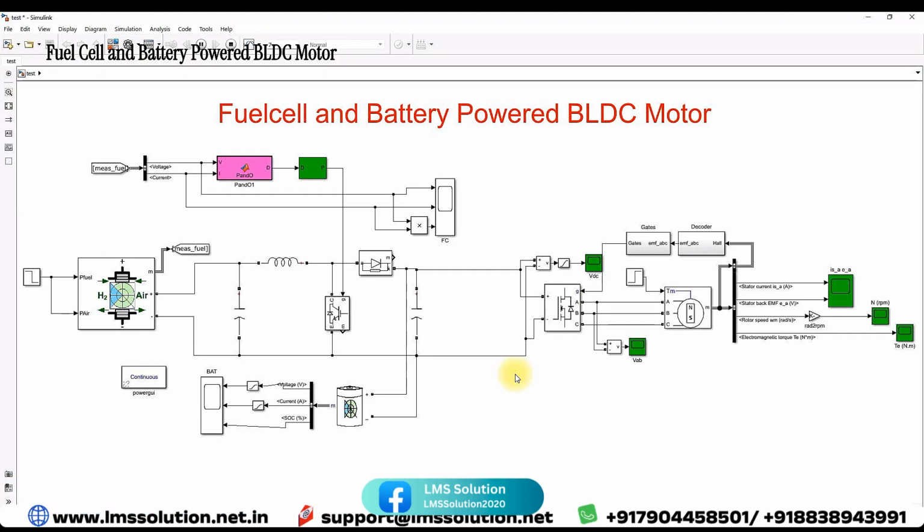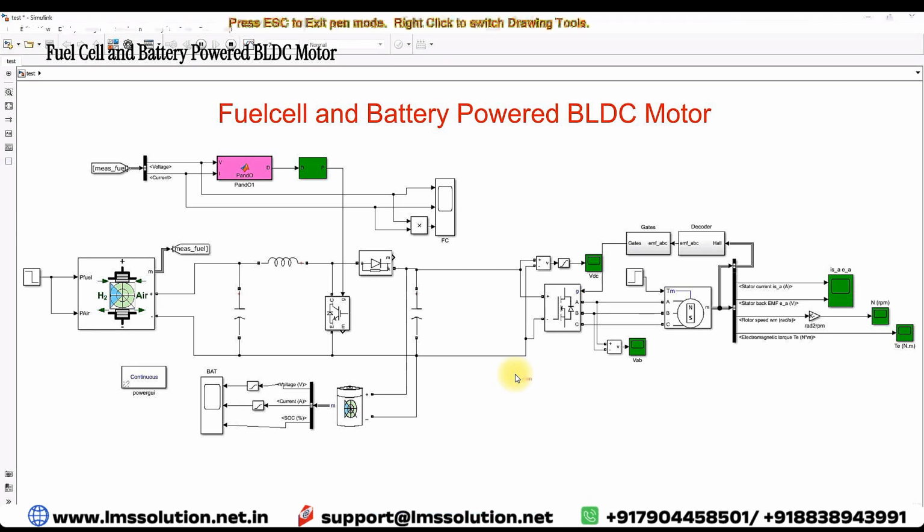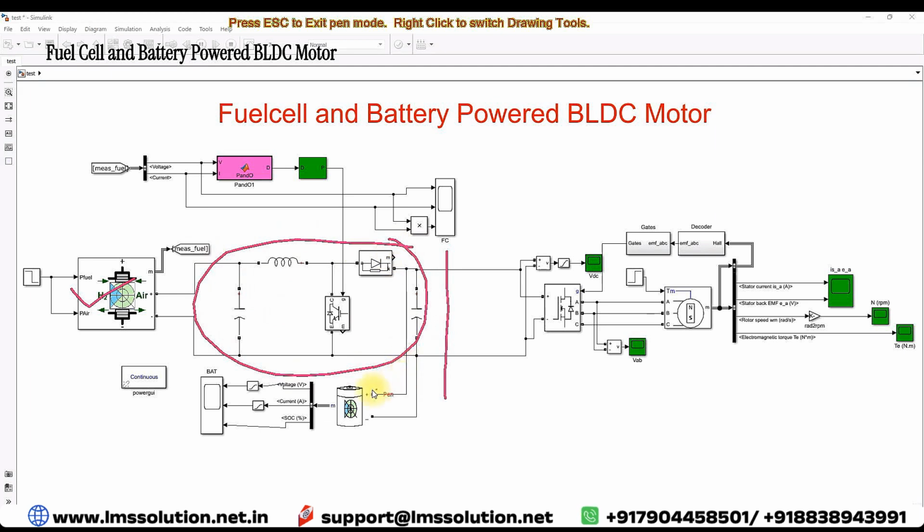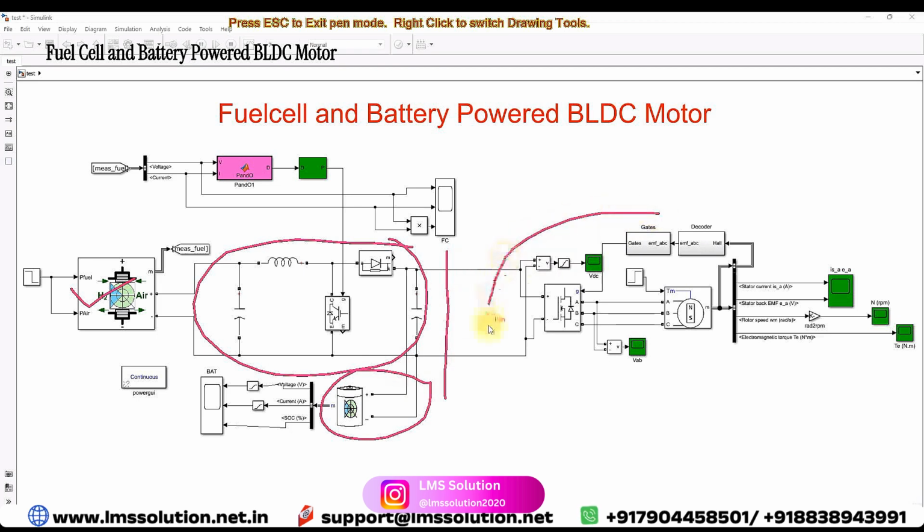Today we are going to see about the fuel cell and battery powered BLDC motor, and this is a simulation model we developed for a fuel cell and battery powered BLDC motor. This simulation model consists of a fuel cell, and the fuel cell is connected to the common DC bus via this boost converter. In the common DC bus we are using a battery, and we are also connecting the BLDC motor.